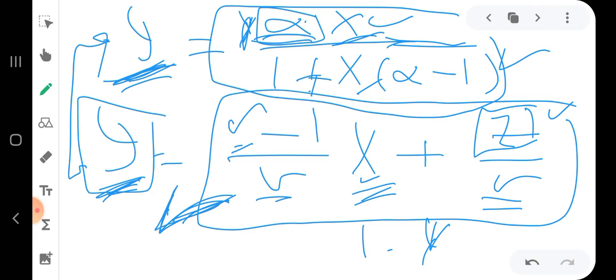But the first equation contains the relative volatility, and we assume it is given and it is constant. So if we are not given a constant relative volatility, we need another way to solve the problem. The other way is to use the graphical solution.